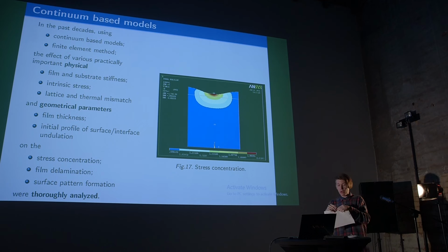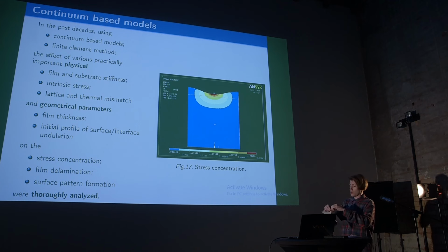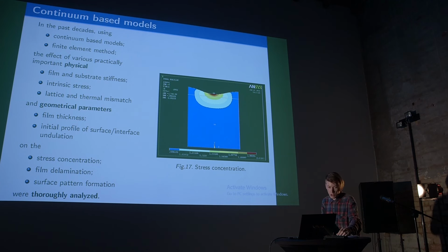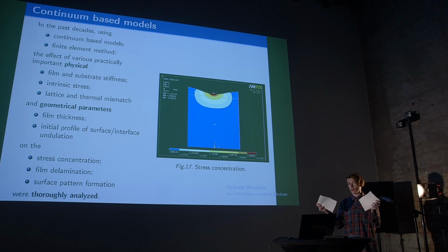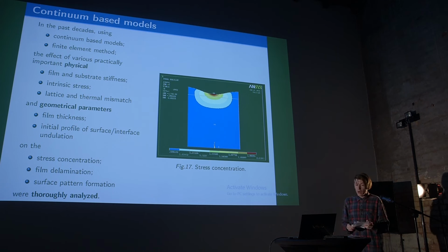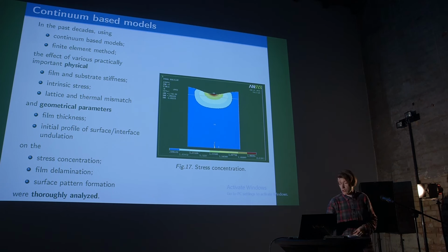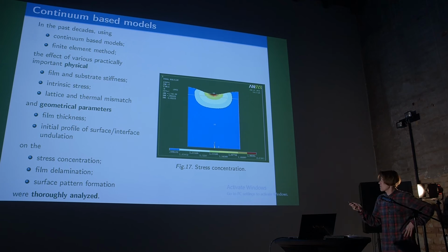But if we make some surface defect, for example, we can make such kind of notch, it will be quite easy to break it. Why so? Because wavy surface generates very high stresses.